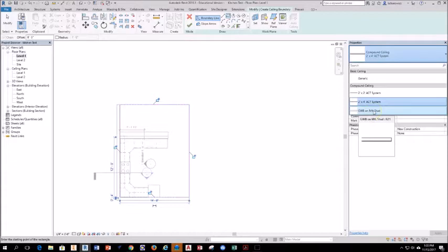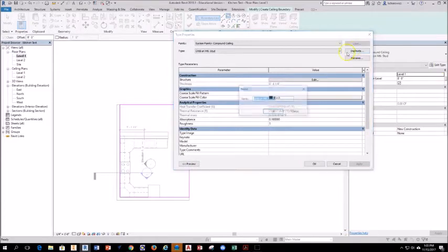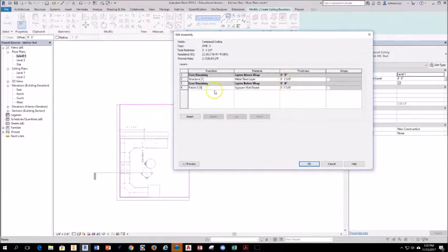In fact, the ceiling is going to be installed on the bottom of the floor joists that would be holding the second floor. So what I'm going to do is select that gypsum wallboard on metal stud, hit Edit Type, and then duplicate. And instead of having gypsum wallboard on metal stud, I'm just going to say it's GWB, and I'll put in 0.5 because that's going to be the thickness of my drywall. The drywall would really be structurally held by the floor system that's holding the second floor. So GWB 0.5 for 1/2 inch, and then I'm going to change the structure.